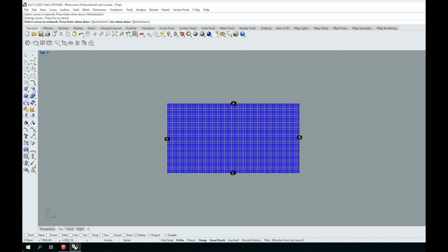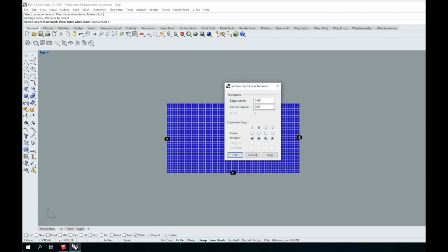Give it a little bit more time. There we go. If your computer's having trouble processing this data, you can eliminate one of the zeros. So eliminate a 0 there, and we'll eliminate a 0 here. That lets us work at 0.01 and 0.1. It may take a second to adjust because it's actively previewing. And then you can go ahead and say OK.